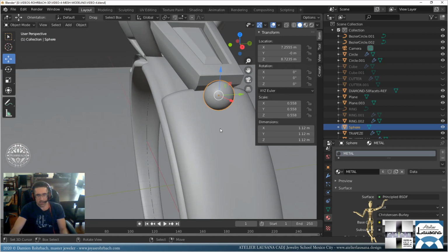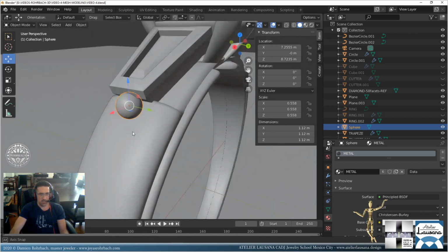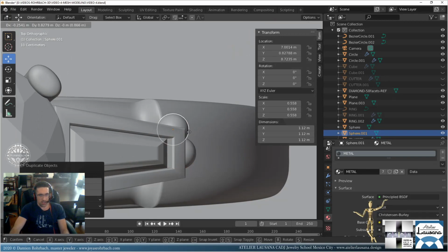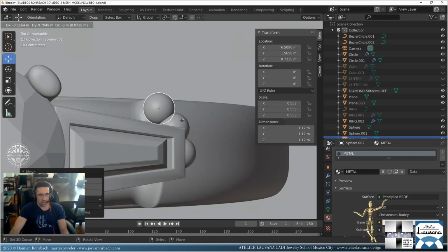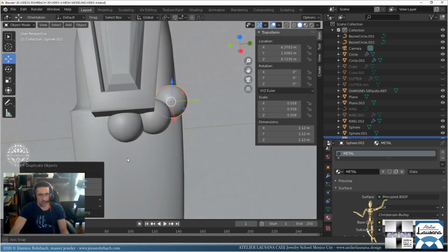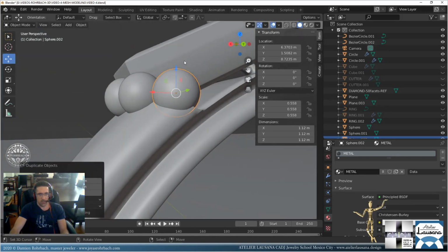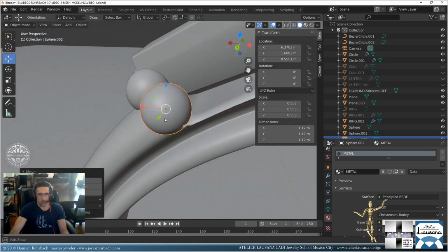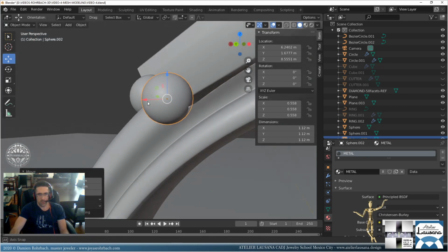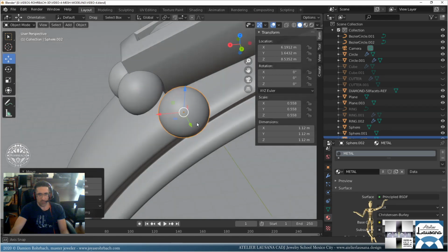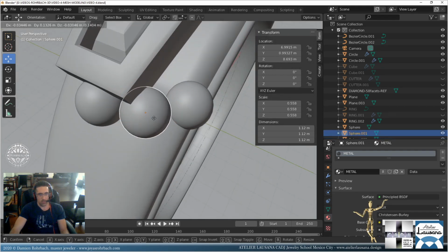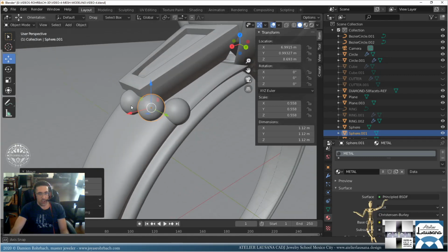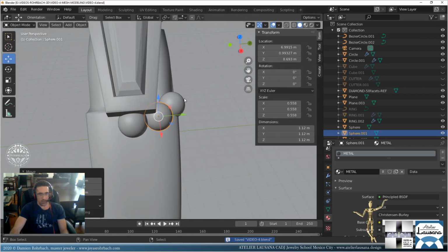Okay. I have that. Let's make a Shift D, G, Shift D right there. Okay, that's a nice option. That's better. It's going to look better. Okay, I don't want that sharp corner there for aesthetics and ergonomic reasons. Okay, now we have this and that.